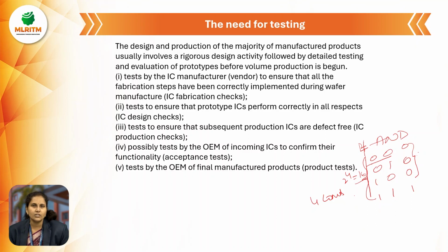I can generate for 2 power 4, 2 power 5, 2 power 6. But if I want to design any circuit with more than 10 or 15 inputs, that many combinations cannot be generated manually. That is the problem in testing.